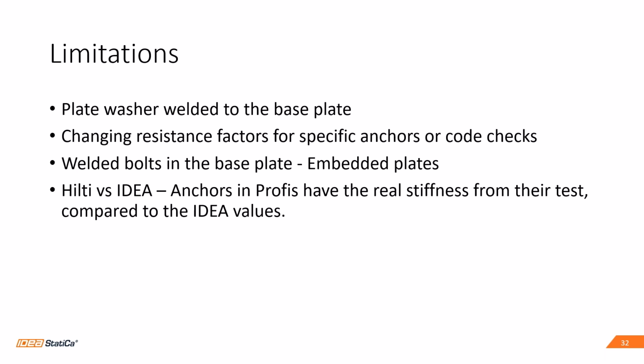Finally, if you want to compare anchor code checks and anchor calculations from Hilti Profis versus IDEA StatiCa, you won't get the exact same values. Why? This is just because anchors in Profis have the real stiffness from their tests. Of course, they have their own anchors, their own products, so they have the real stiffness. So that's the real stiffness used in Profis. Okay, so if you compare those, you won't see the same results.